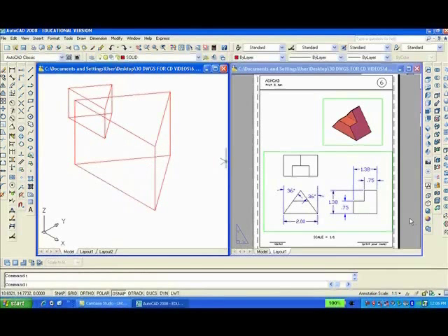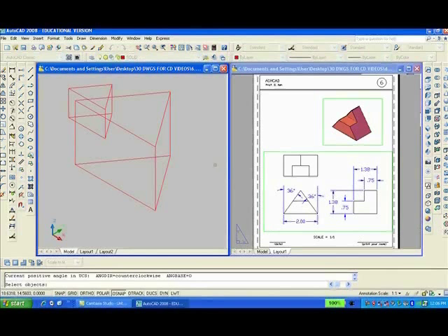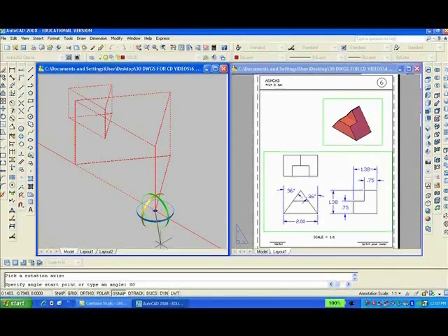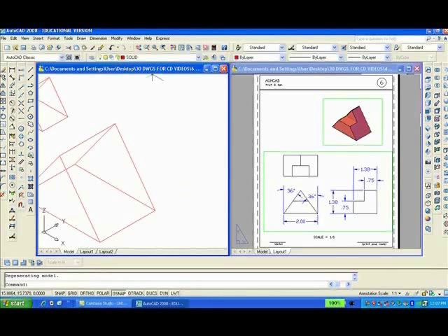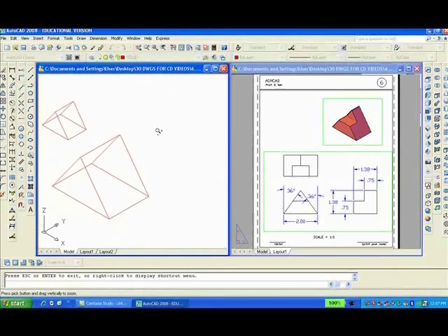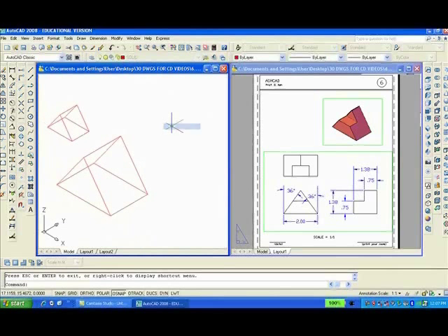And I'll go to the 3D rotate command and I'll select both triangular blocks, pick a point, and I want to rotate them counterclockwise, so it's simply 90, enter. I'll shrink it down so I can see them better. Now I want to move, enter. I want to move that small block, enter, from this base point here in the front.